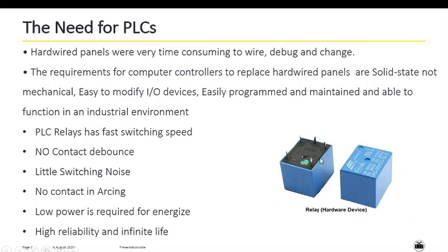So this is our conventional relay which we are using. These are the primary windings to which we give a supply from one side. If current flows through this coil, it will get energized and connect the supply from NC to NO. So this is one terminal, normally closed, NC.